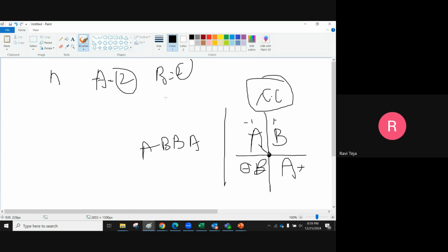So what happens is, I told you, right, process variations. If at the time of fabrication the etching is from this side, the amount of etching variation on A will be the same on B. Okay, the major consideration is this.